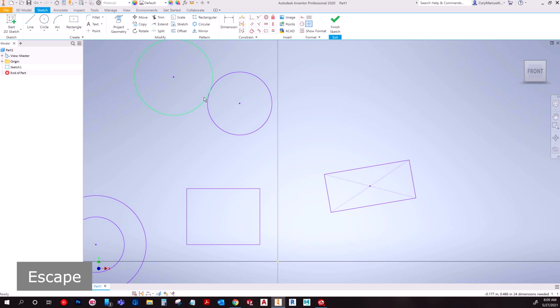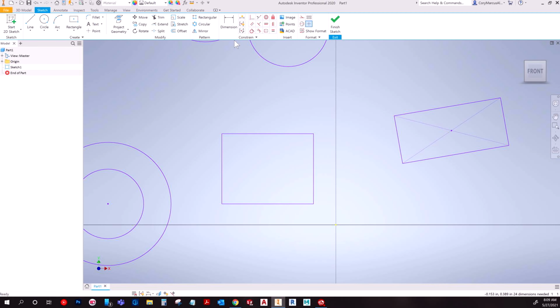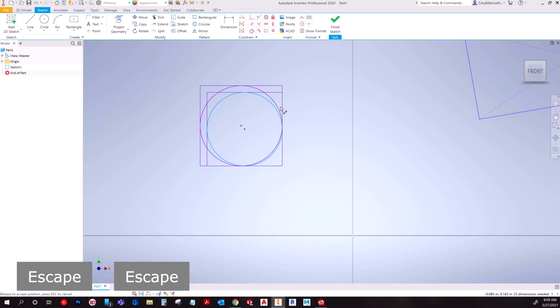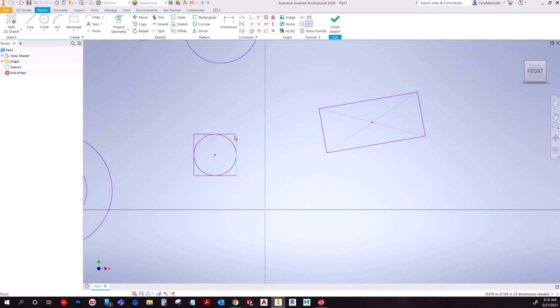And the same deal, if I had a line that went through all of this, I could trim half the circle, and you would basically have a fillet that transitions into a fillet. One more use case, which I kind of like: say you had a rectangle that was equal in size. If you don't know the location of the circle, but you know that it touches the corners all perfectly, you can choose each line. And just like that, it matches the size of the rectangle. So now they're obviously tied together, and it got super gigantic. But that's one cool use case for it too.